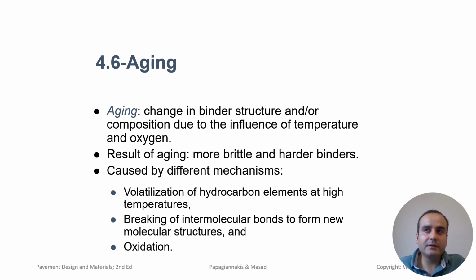Aging is one of the critical factors that affect the long-term performance of asphalt binders. As binders age, they become stiffer and more prone to cracking due to oxidation and exposure to environmental factors such as heat and air. Aging occurs in two primary phases. Short-term aging happens during the production, transportation, and placement of the hot mix asphalt.